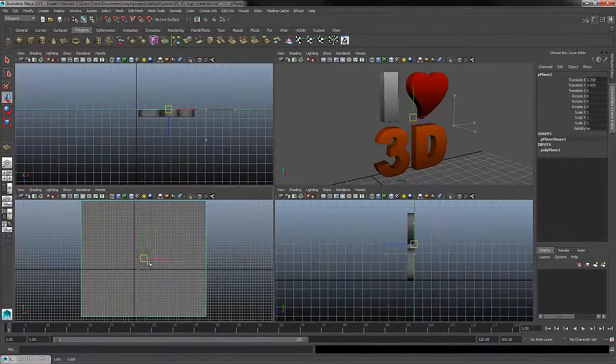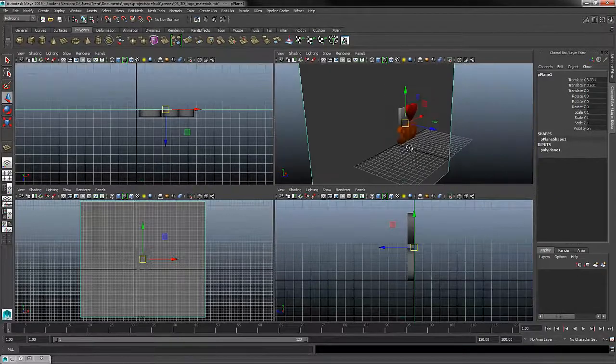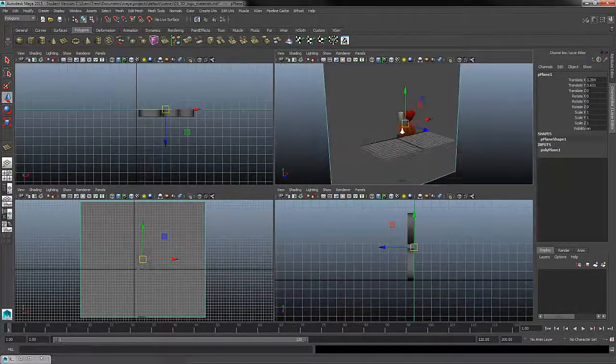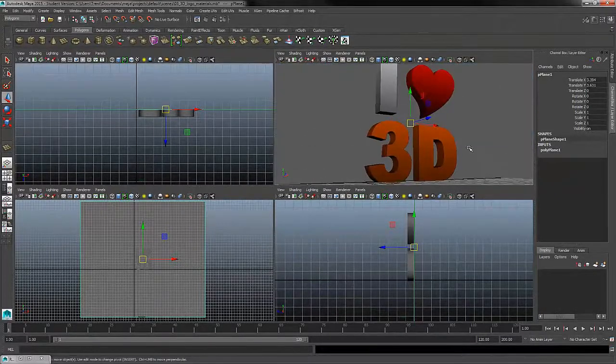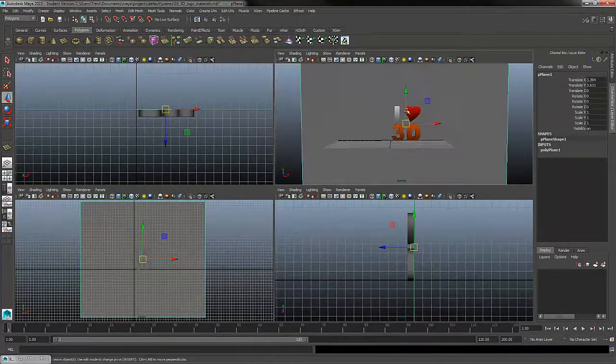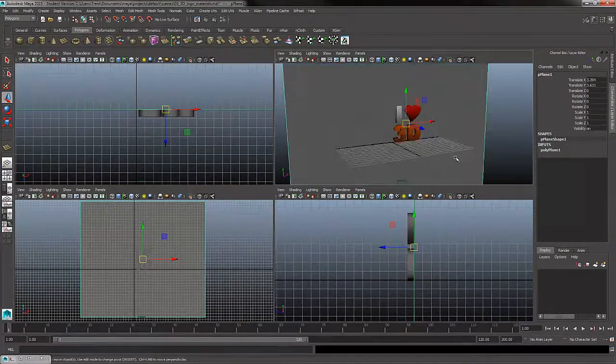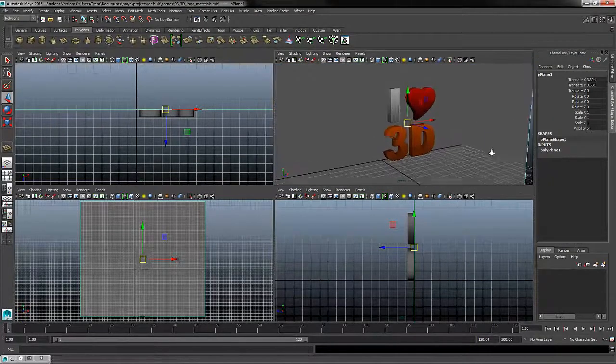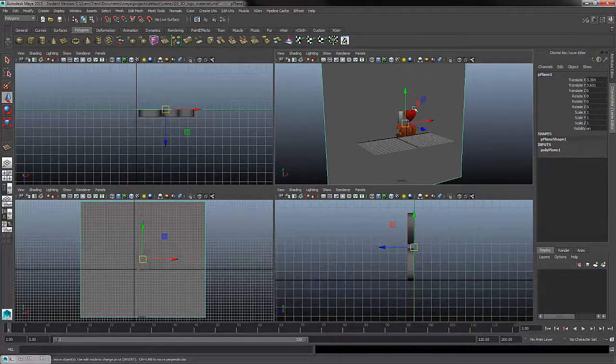Now I'll just center this up on my logo approximately and take a look at this in my 3D view. You can see I created it nice and large. That way if I look from different camera angles, I won't be able to see the background in behind. So I could assign a color to this. So the exact size isn't very important. I just made sure it was large enough that it would be larger than my camera view.